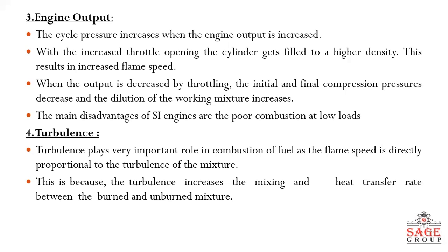When the output is decreased by throttling, the initial and final compression pressure decreases and the dilution of working fluid increases. The smooth development of self-propagating nucleus of flame becomes unsteady and difficult. The main disadvantages of SI engine are poor combustion at low load and necessity of mixture enrichment, which may cause wastage of fuel and discharge of unburnt hydrocarbon and products of incomplete combustion in the atmosphere.